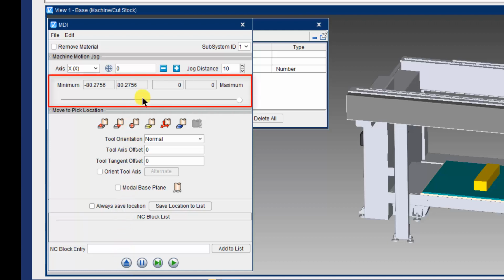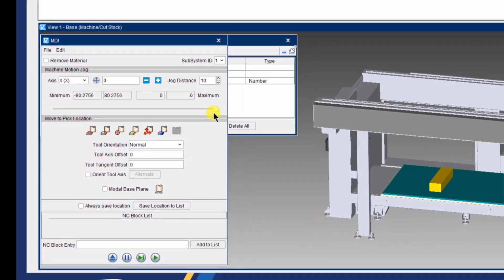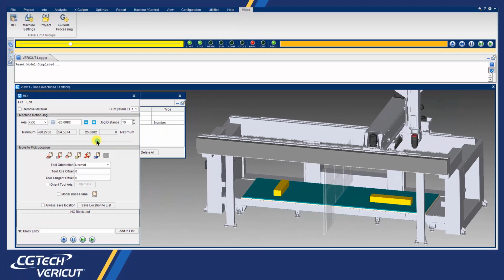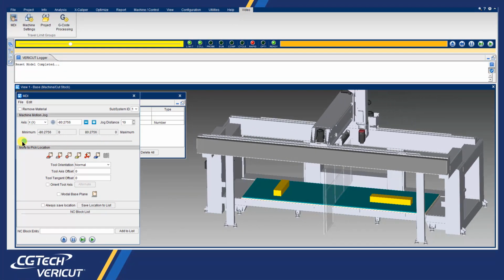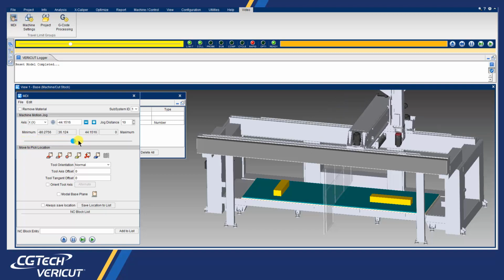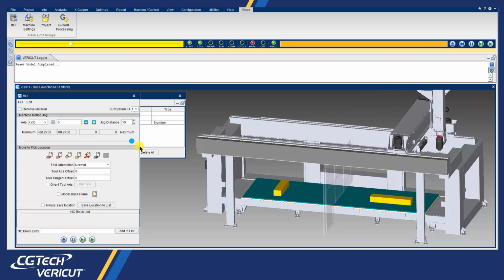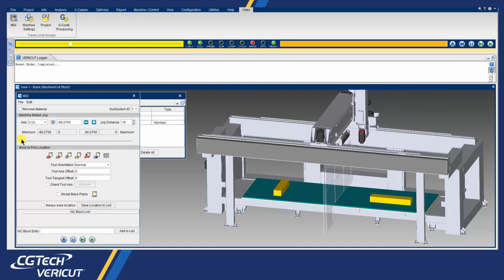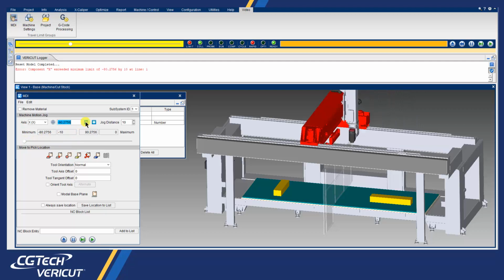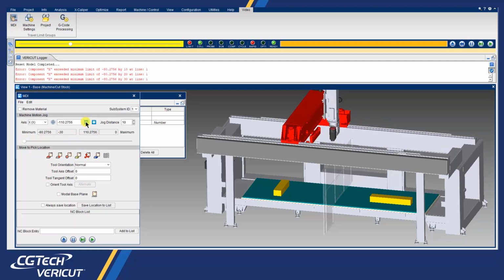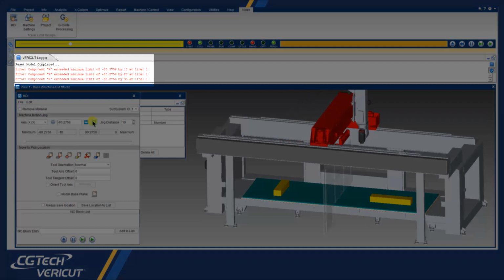Using MDI once again to check the revised travel limits, we can see that an over-travel is reported if the machine moves outside the right-hand workspace envelope. The travel limit group macro could also be used with a program M code if these zones were changed programmatically.